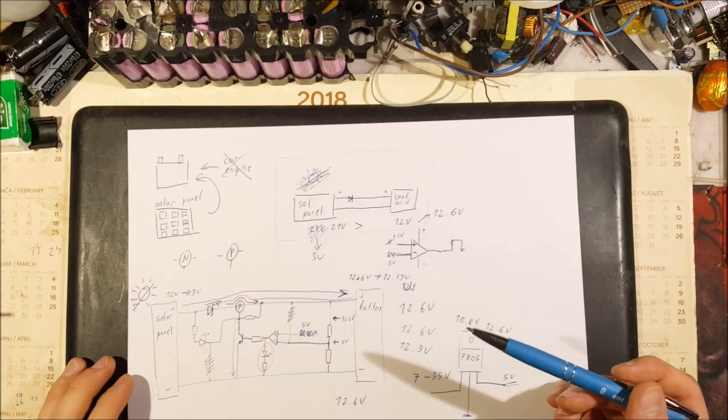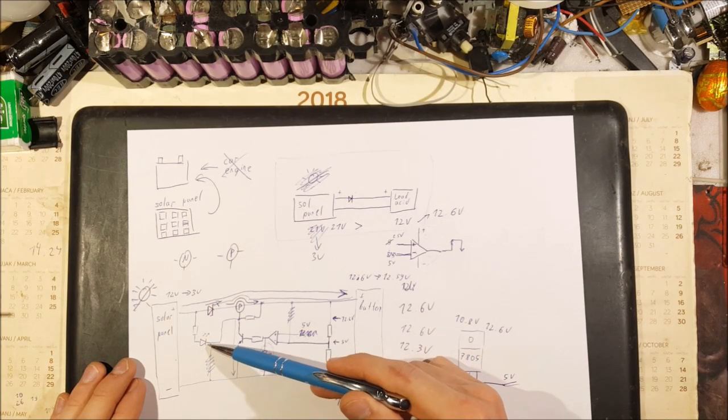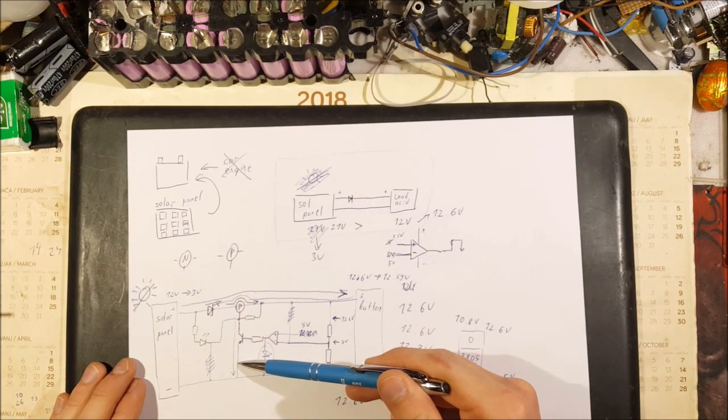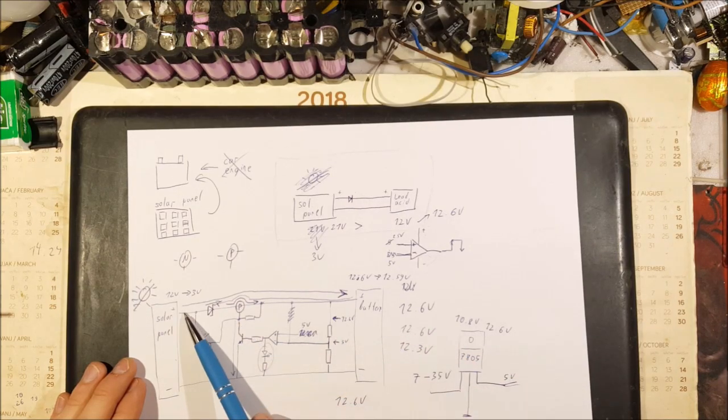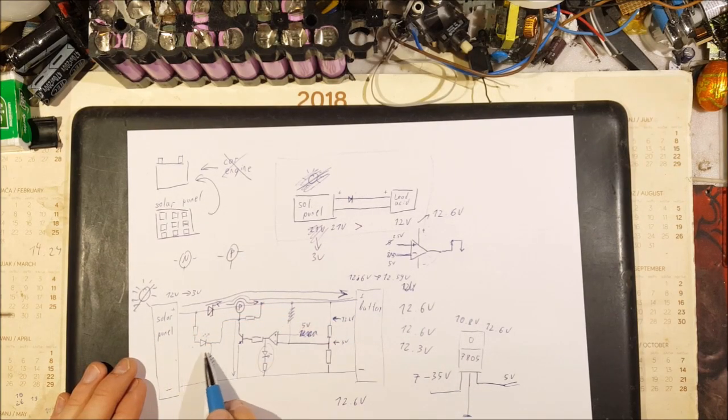And even if this transistor is pulling the diode's negative wire straight to ground, and there is no voltage on this pin, the diode still won't turn on, because the voltage difference across the LED is still zero.